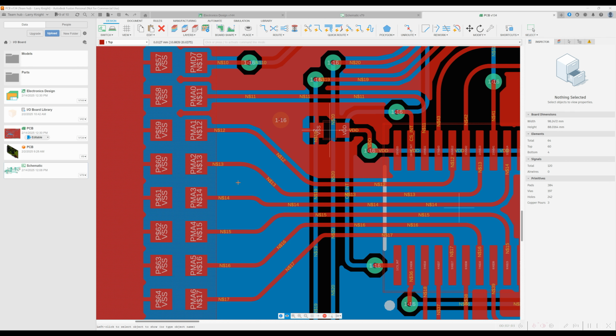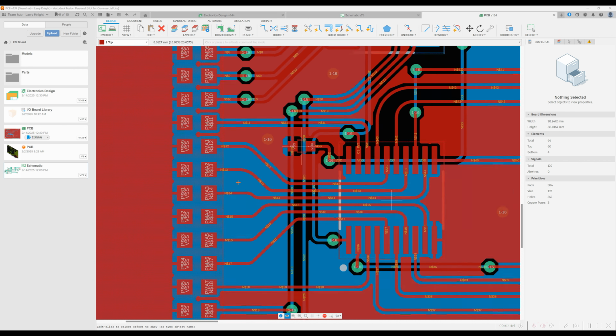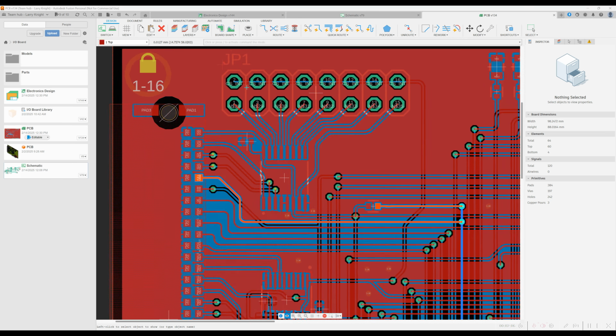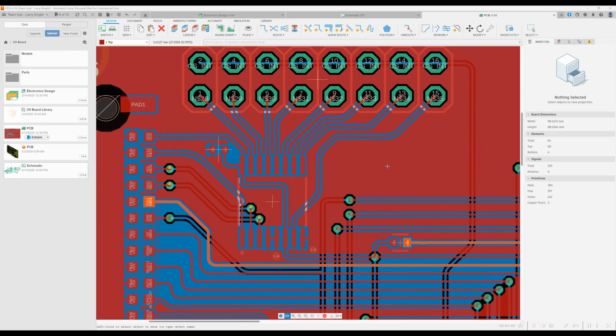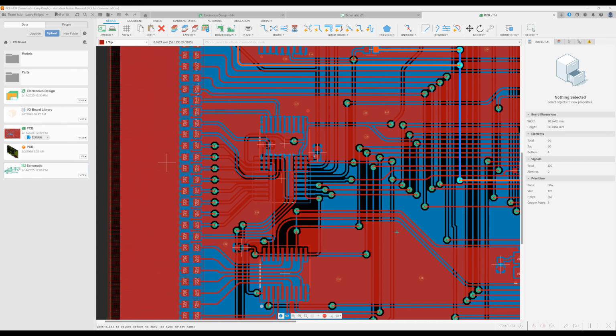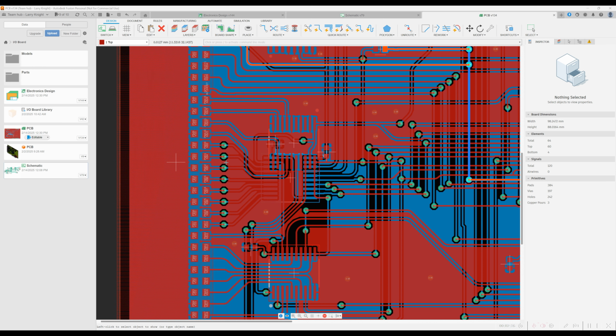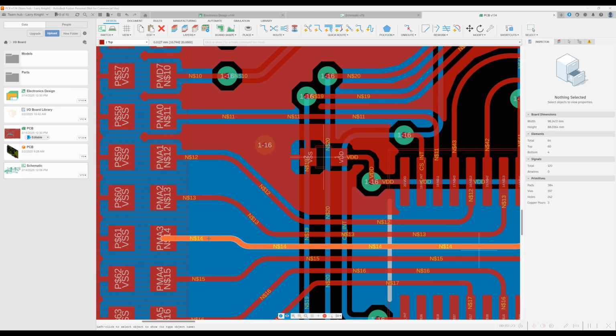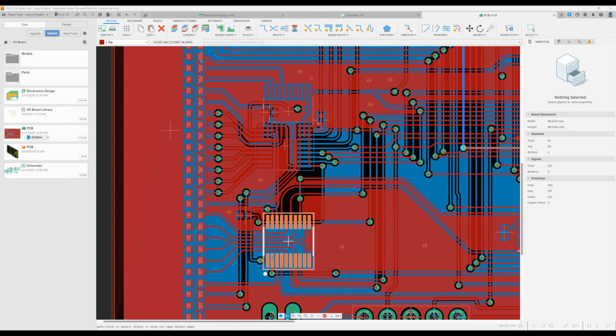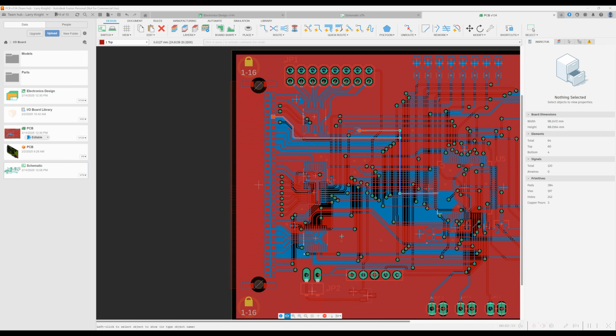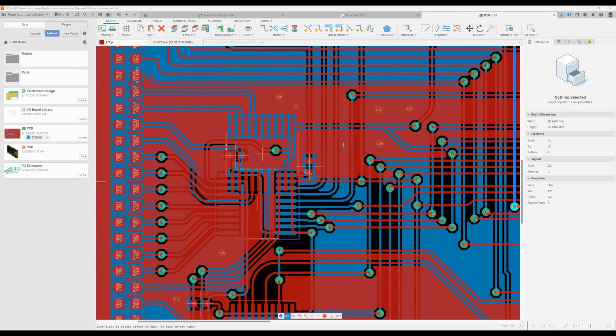All right, and then we'll switch it on up here at our jumper. We'll put it on A0 and select these guys. And then the resistor should not be able to pull up the address lines. It should remain low, at least on this chip here, because these are being forced low from the other side. So I think that's a good test.